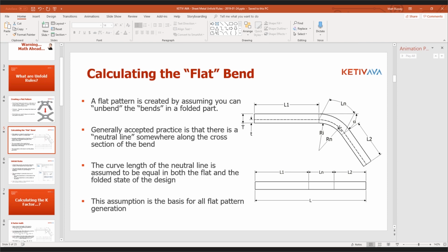When you bend metal or bend anything, it is not a linear deformation. One of the assumptions I glossed over is that the thickness in this bent state is exactly the same as the thickness in the flat state. That is not true.